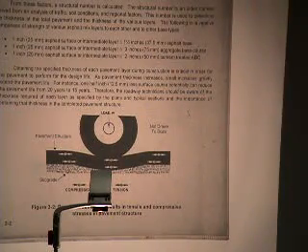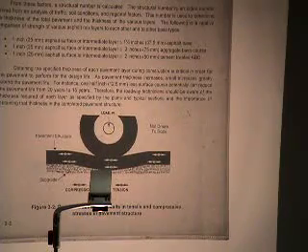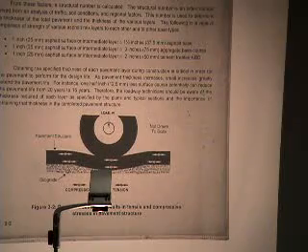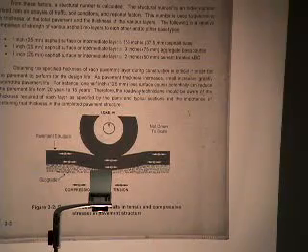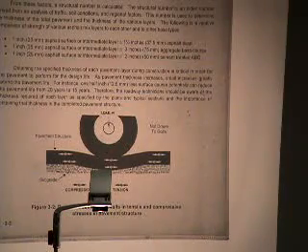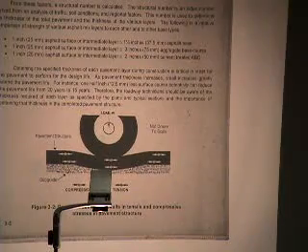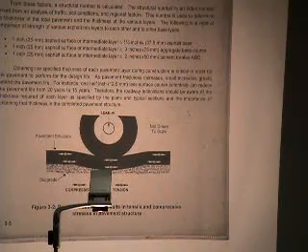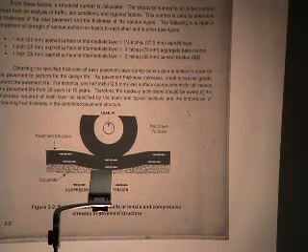When a vehicle moves along the pavement, it's constantly causing deflection in that pavement. And it's sort of like when you take a piece of wire or a metal bar, and you can bend it a little bit, and as long as you don't bend it very much, you can put it through many cycles before eventually maybe it'll start cracking and breaking. But if you want to really make it crack and break in a hurry, what do you do? You bend it a lot. And that significantly reduces the number of cycles that it would go through before it starts cracking and breaking.